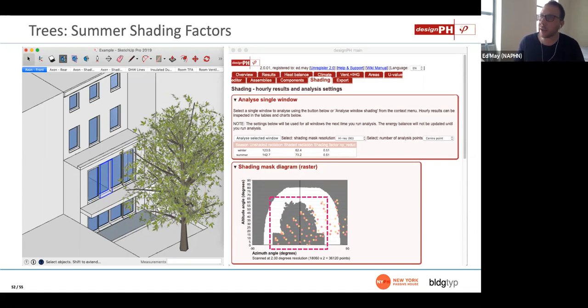Tom asks, is there a toggle ability to go between geolocation and design axes? Do you have to reset the design axes each time? You have to reset it each time. Unfortunately, to my knowledge, you can't save a construction plane to toggle back and forth, sadly. What we'll often do is draw in some temporary geometry, just like a cross or something, that shows our rotated geometry. And then we can use that to snap to, so we can easily get back and forth between it. But you do have to physically reset it each time when you change your design axes, unfortunately.